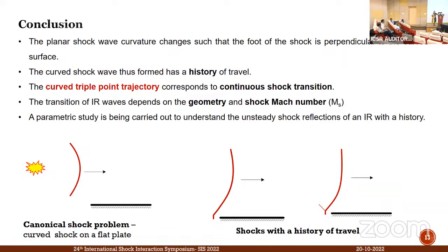Yes. Actually, the same thing happened in the previous results also. What we understood is the flow itself is not having a constant velocity. It's completely unsteady by itself. That is not the problem. You have the initial flow coming, then probably the flow may be going slightly transonic behind that when it passes over that sharp curve. But expansion fan, I don't find the reason for an expansion fan there. It may be a supersonic patch forming by some other reasons. I don't know.